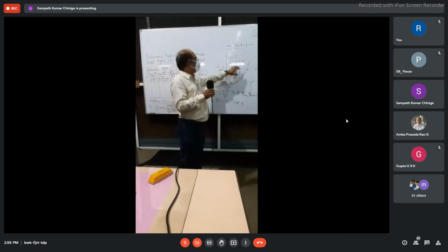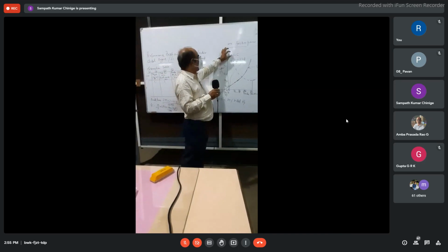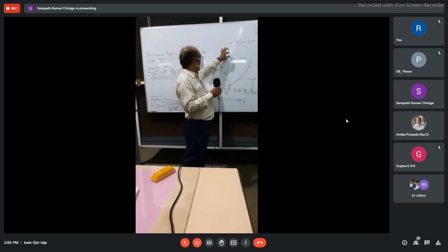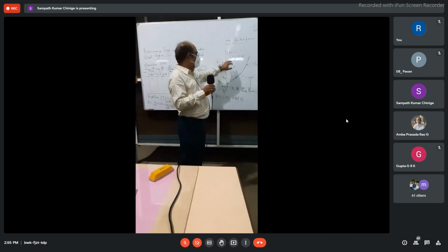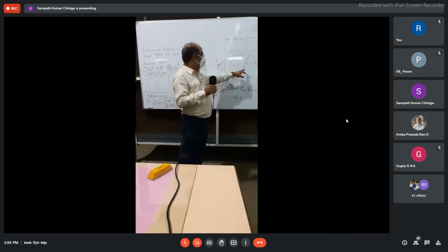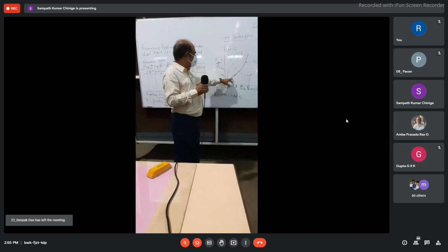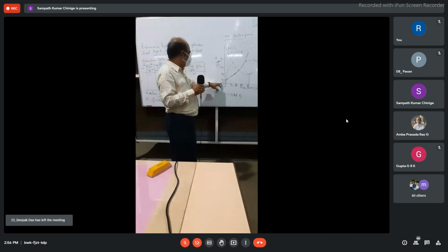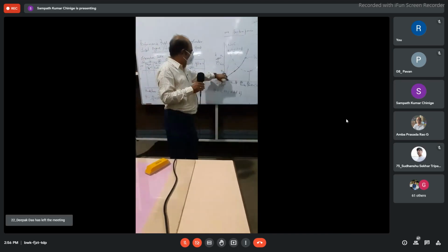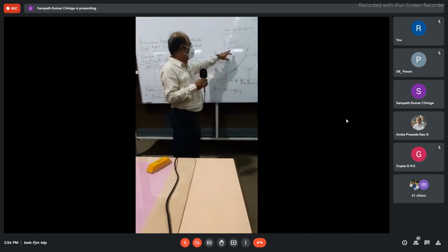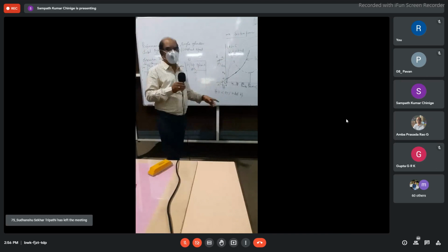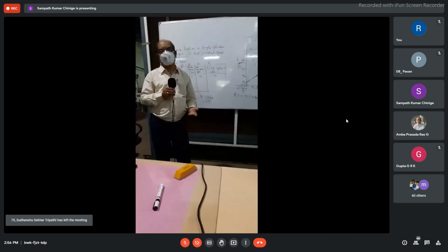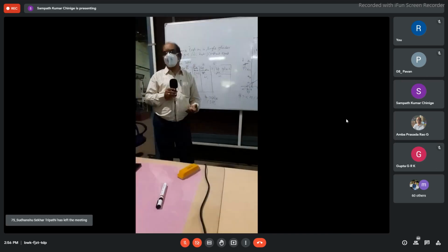This is applicable for engines which are running at constant speed, and moreover for unthrottled engines, and a diesel engine is an unthrottled engine. Likewise, you get the curve here. By extending the linear portion of the curve, as I told you in the previous class, you will get this value, and this value is a constant because the speed is maintained constant. This value needs to be added to every brake power value to get the indicated power value for every torque meter reading.